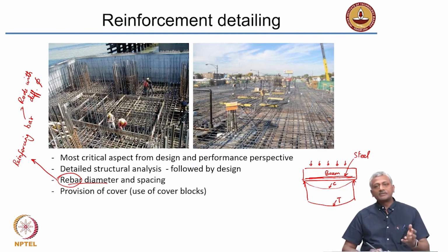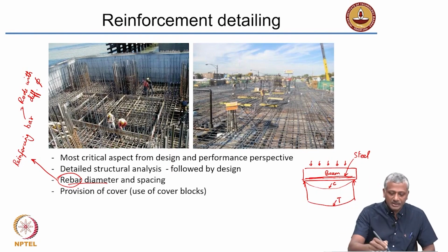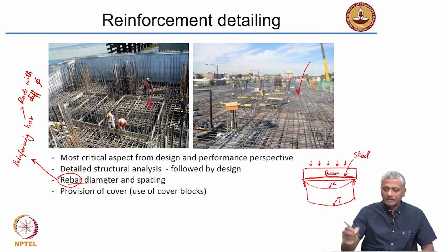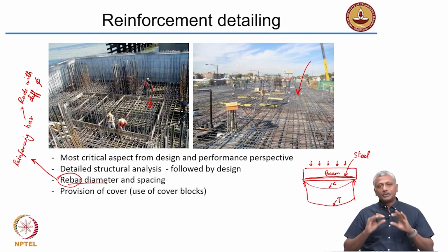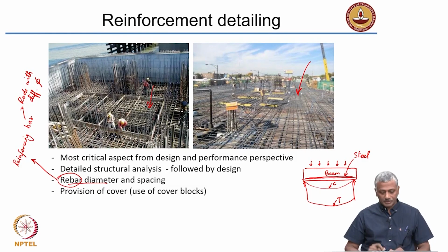All of this you will learn in more detail when you encounter courses on reinforced concrete design. But it's very important to understand that before the concrete placement into the formwork is done, the reinforcement has to be appropriately designed and laid out, like you see in these pictures here. The reinforcement is properly laid out before the concrete is poured to ensure that you are getting reinforcement in all the zones which are going to be experiencing tension.